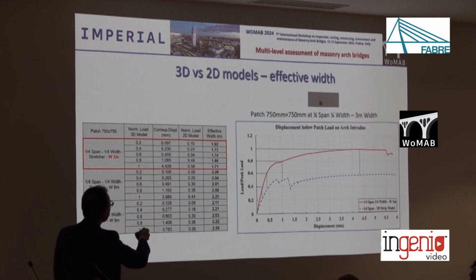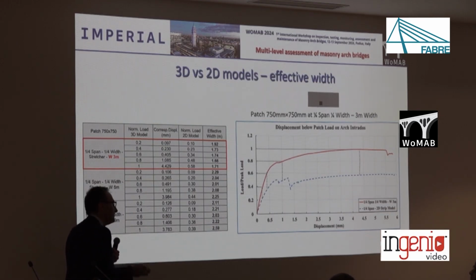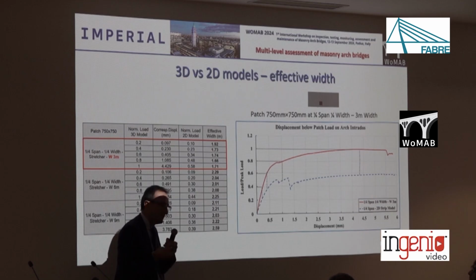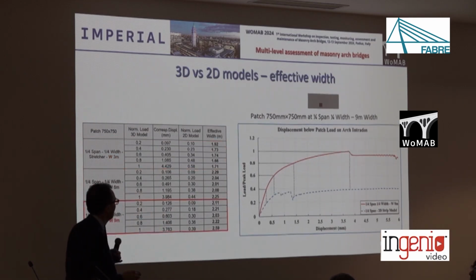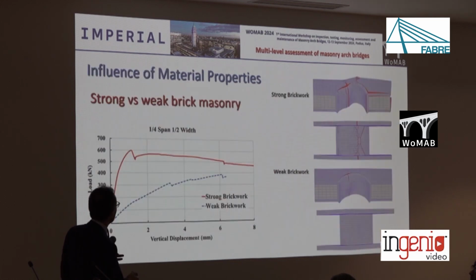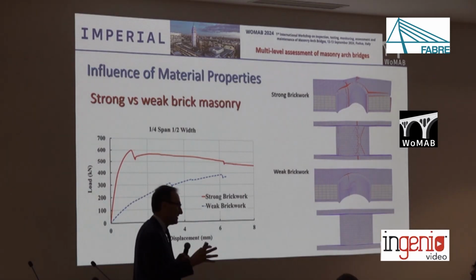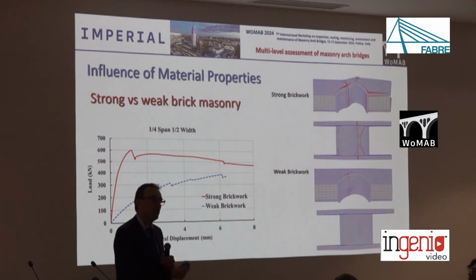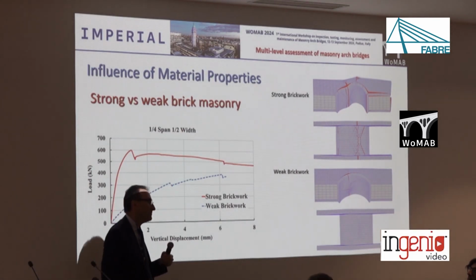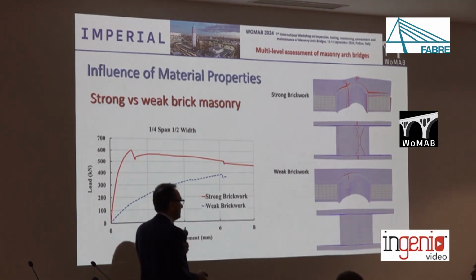And we see that it doesn't change much at different loading levels, and actually in this case we found the value is not very different from the value recommended by the standard, which is fine. It's fine until a certain point. So if we consider, for instance, weak bricks, right? In the previous simulation, we assumed strong bricks, as in the original experiments. Engineering bricks with very high compressive strength and tensile strength.